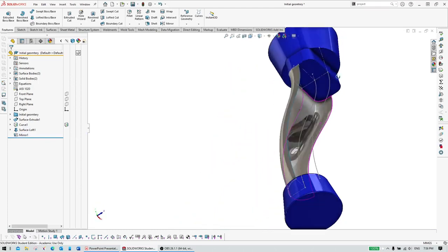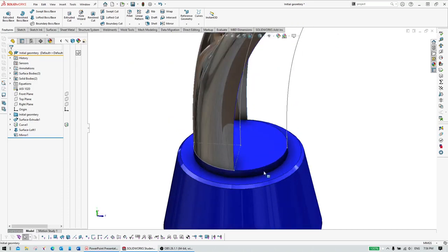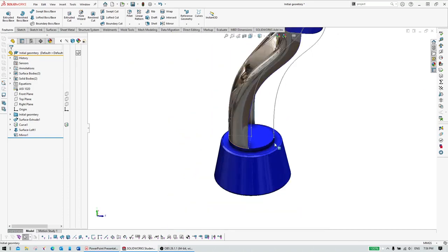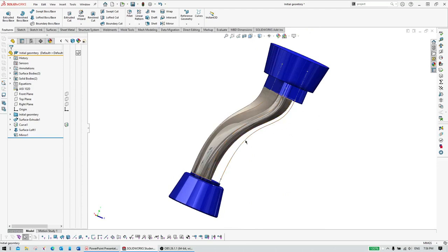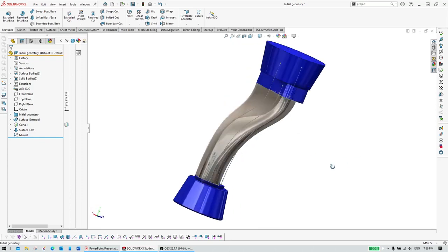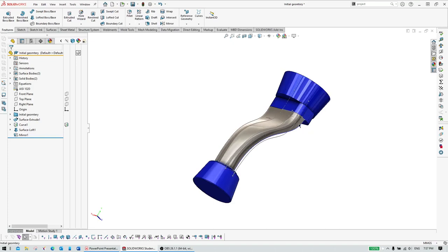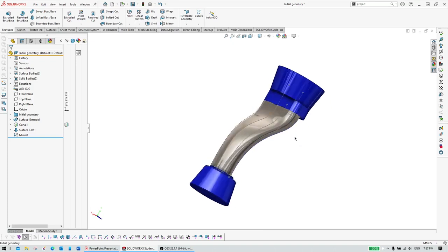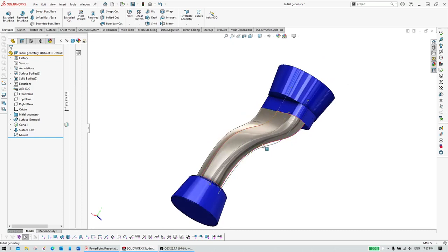On the other side, again, you need to create this cross section, and over here you need to create this cross section as well, and then you can create this lower portion, lower side, and then you can use the mirror command again to create the whole geometry like this. So in this case, as you see, you need multiple steps to complete this. Okay, let's check the boundary surface, how it works. If lofted surface works, it means boundary surface will work as well.